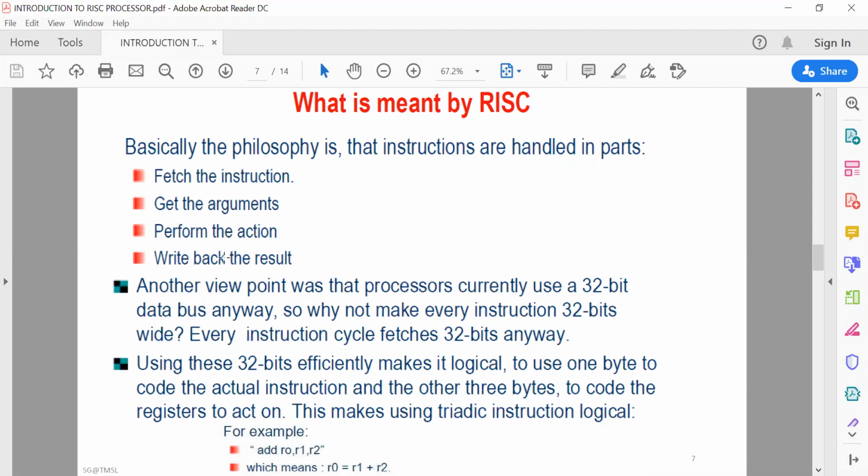As an example, suppose it is written as add r0, r1, r2. Here you need to perform the addition, and the result must be written into another register. All of you know, from the 8085 and 8086 microprocessor operations, that to perform any addition you add two register contents and store the result using the first register as your destination point. Here you can use three registers, where the first is the destination and the other two are used to operate that function.